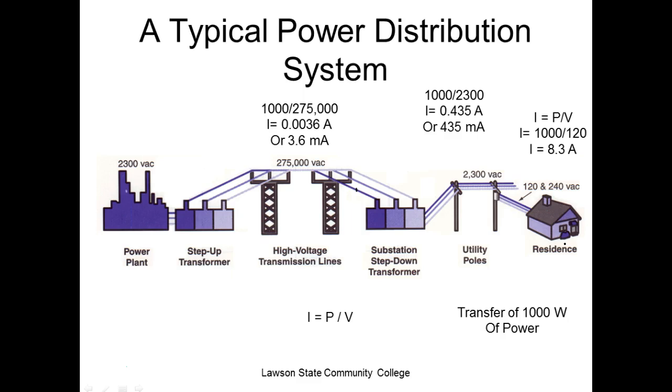Then I get back to my power company. Now my power company is generating at 2200 volts, which is pretty standard. It depends on whether it's intrastate or interstate, how far the power runs, and what voltage. They get up to over 700, I think it's 725,000 volts on some long distance transmissions. But what they can do here, instead of using copper wire, is go back to aluminum. Even though aluminum has higher resistance, the voltage is so high and the current drops so low that they won't have a lot of line loss.